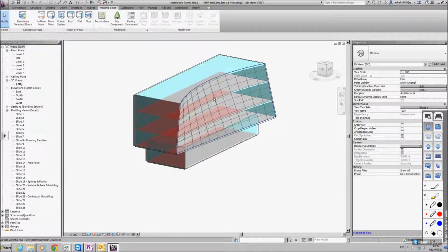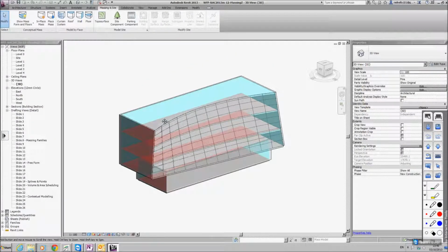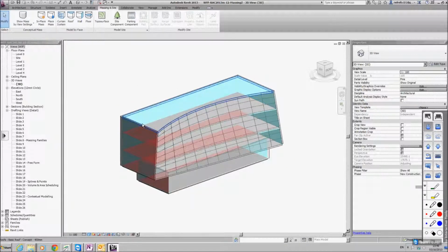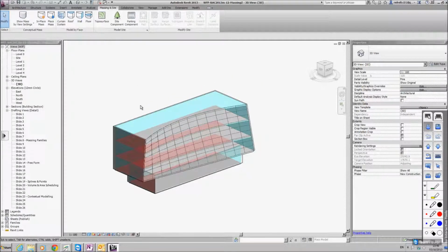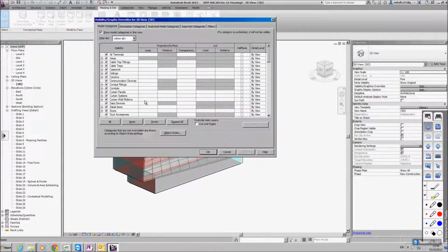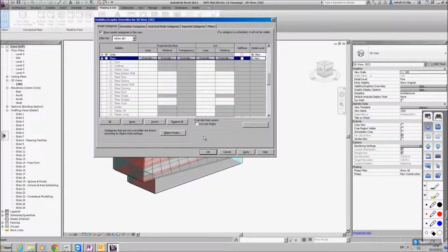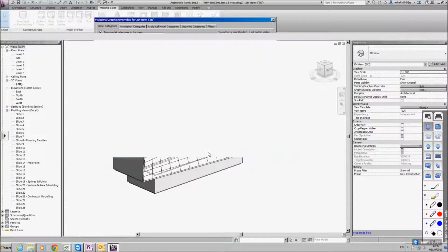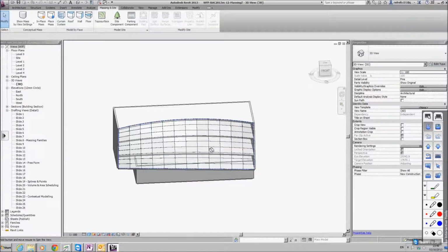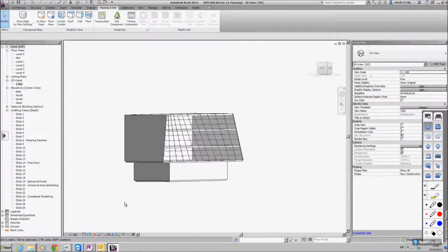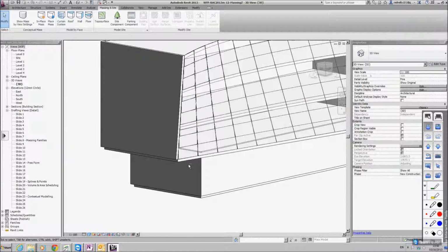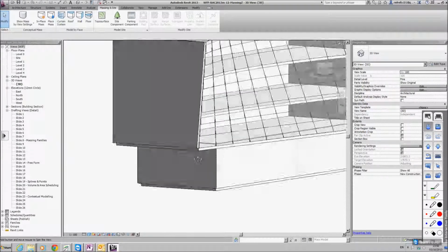And that is a quick look at actually creating your massing object. So I'm just going to click on the mass object in this view, and type VG, and I turn that off, apply, and it's after turning the massing off so it doesn't complicate it and makes it a little bit easier to see what needs to be fixed up.